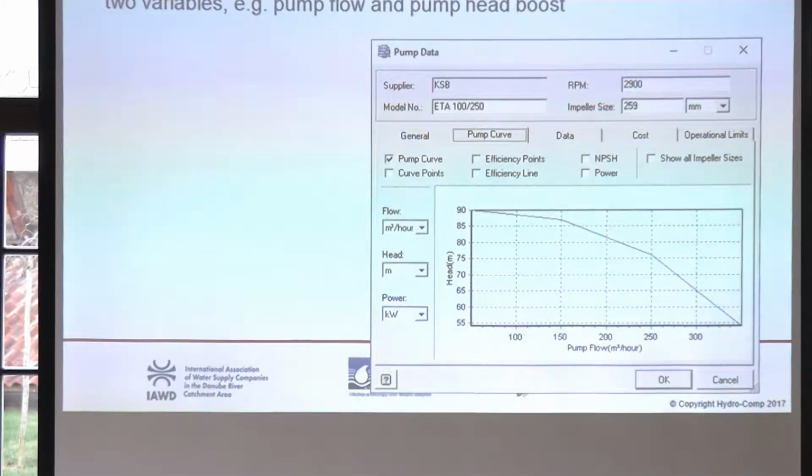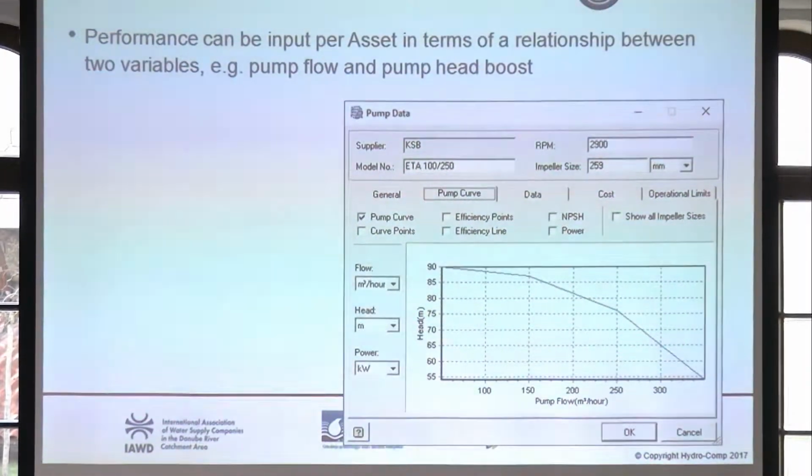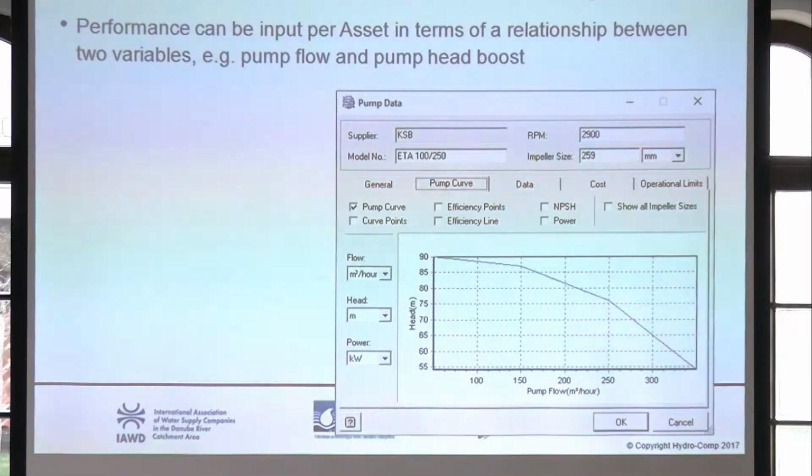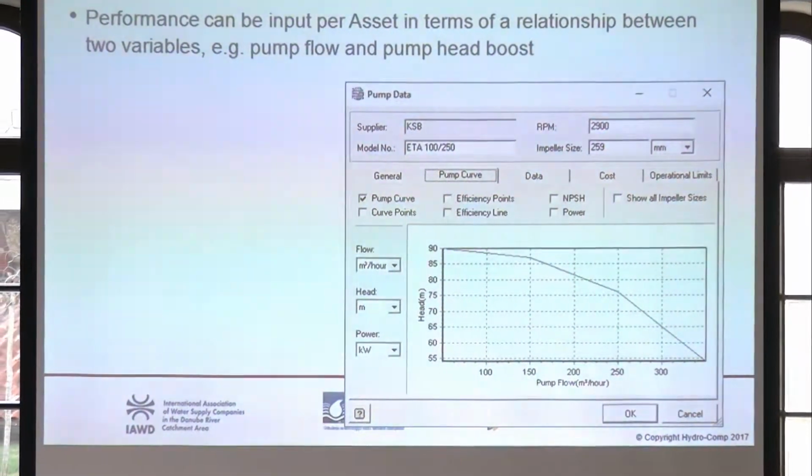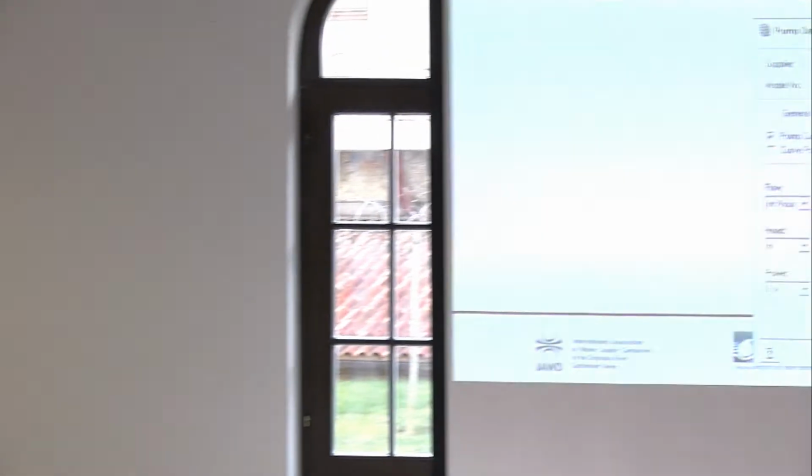And we can take it a final step, if we have all the numbers in. The system, it's a new thing we developed, will automatically tell you how your pumps are doing. I will tell you for every single pump you have if it's working properly or not. Because if I have the duty flow, and I have your numbers, what you are pumping at what head, I can tell you if the pump operates efficiently or inefficiently, and how much it's costing you because of the inefficiency of your pumps. So at any stage, you will know how much money you're losing because of the inefficiency of your pumping and what you need to do to improve it for each one of your components, be it pump stations or boreholes.